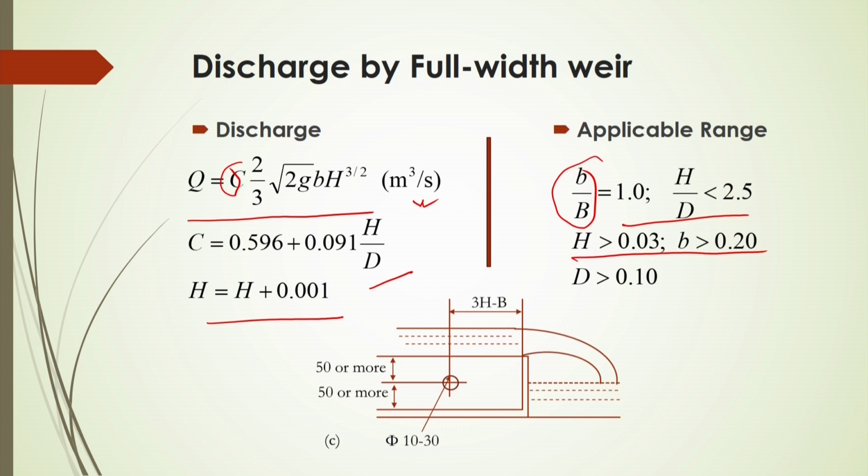So, in this lecture we got the idea of the principle of how the different flow meters work, other than the conventional way of just getting the drag force, pressure force, all those things. These flow meters are basically based on the oscillatory mechanism, the sonic wave, as well as the vortex frequency.